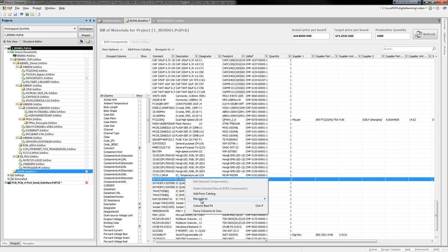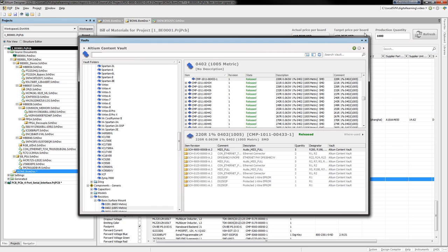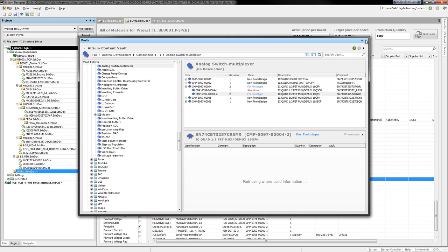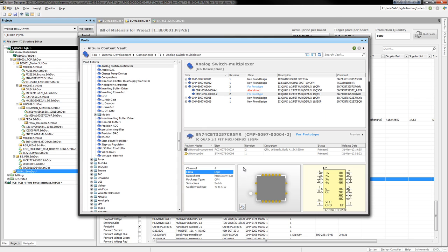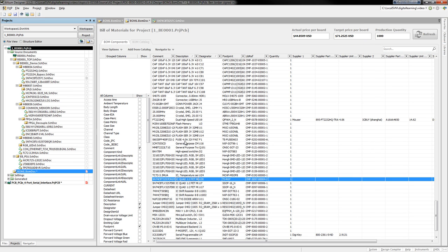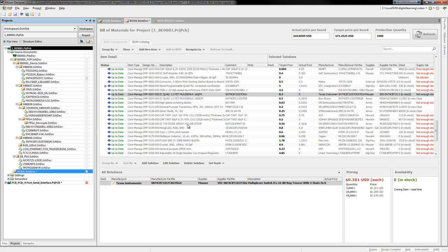Not only are components brought into the ActiveBOM as you place them in your design, there are times when it's appropriate to work the other way around. That is, to add components to your items you know will be needed before you've even begun the design process that electrically links them together. To that end, you can add item instances to the ActiveBOM document from the Vault as well, like the PCI Express templates shown here.